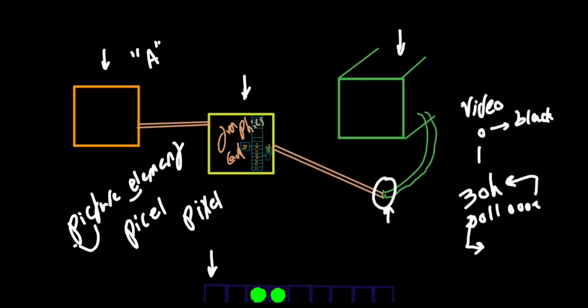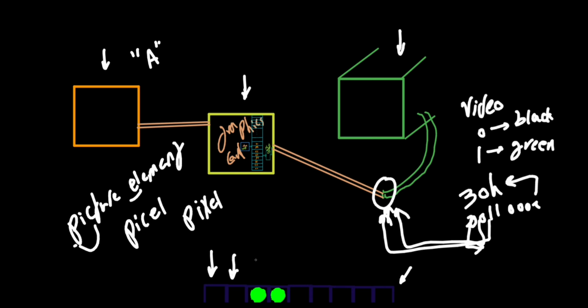Also pay attention that these borders are not real. I've just shown you these borders so that you could see them. Next, the graphics card would give this 0 on the VDO pin. Therefore, the second square would also be black. Later, 1 would be given on the VDO pin, and since the VDO pin is 1, the display would show the foreground color, green. So we would have green in the third square. The next one is also 1, which results in the display emitting light, so we would have green here too. The next 4 are 0, so we would have 0, 0, 0, and 0 in here.